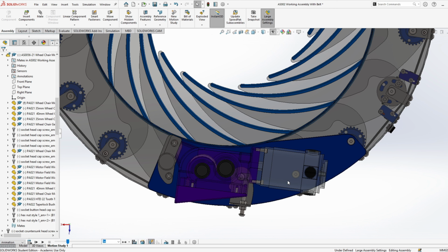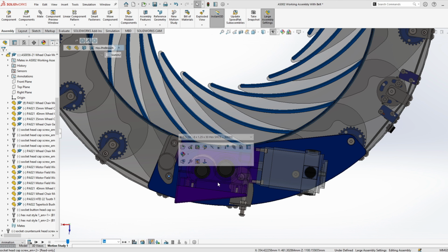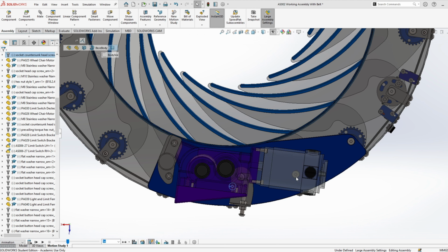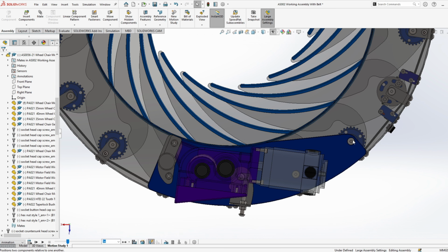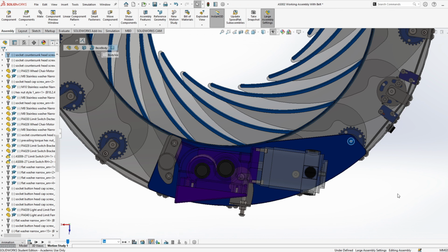So here you can see the 4, if I was to click at this point, and underneath this bracket we have another bolt here, and we have a bolt here, and we also have one here. So these 4 bolts are new countersunk bolts attaching the platform to the sturdy tapped shafts, where the 4 bolts pass down through the 4 upper brackets' existing holes.